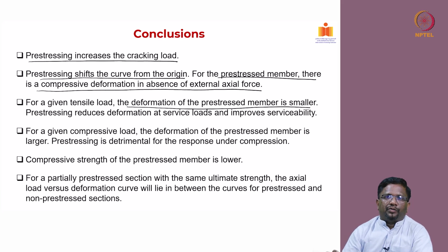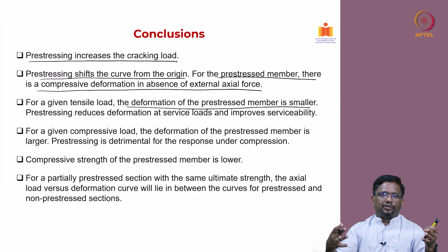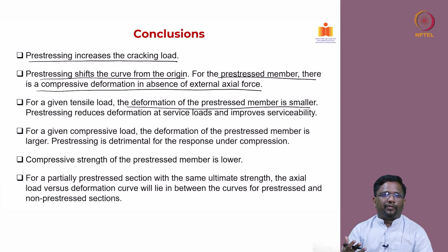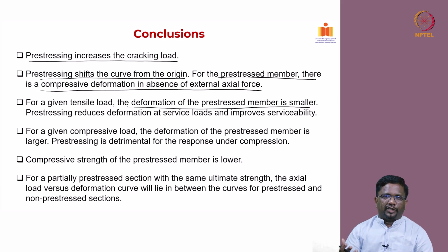So, if your service load levels are fixed, then going for pre-stressing will help you to reduce the amount of deformation that you will have under tension loads. Typically, flexure will create tension. So, deflections are created by flexure.